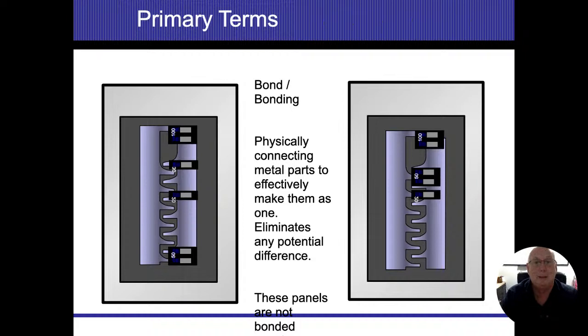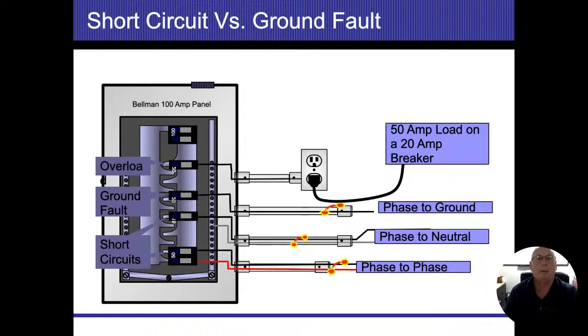So my main bond connects my grounding system to my neutral system. My grounding system will only flow 5 amps, not enough of a flow to trip the breakers. So I need to have unlimited flow of amperage to allow that breaker to trip. All right. So in this situation, we'll talk about bonding, and we'll get into that again, and we'll build a bond in the sub panels, and how we don't bond.